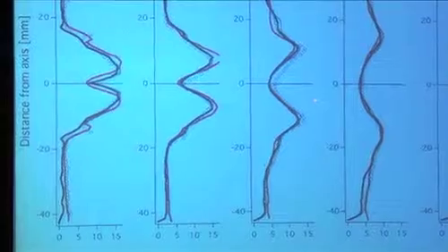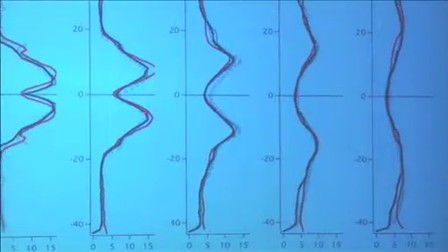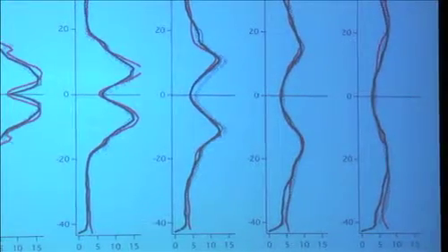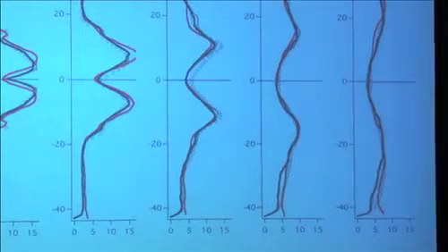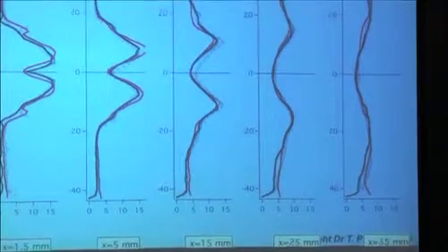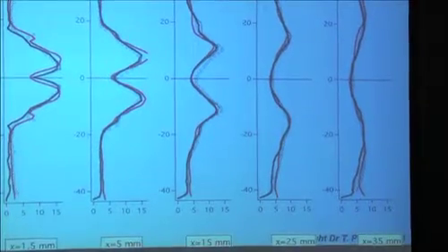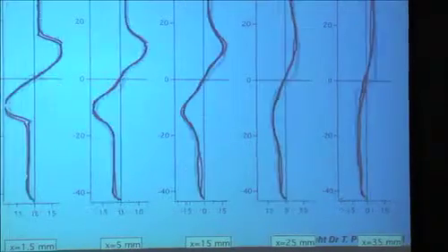The second thing you see is that LES is doing amazingly well in predicting the level of U prime. Remember, U prime cannot even be obtained with RANS because you don't have a U prime. You have K, the total kinetic energy, U prime square plus V prime square plus W prime square. You don't have the individual components. So LES here is really doing very well.